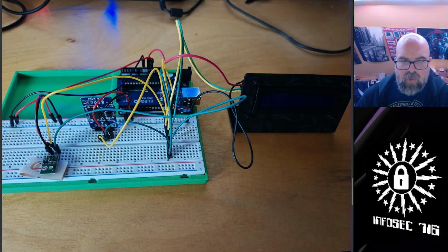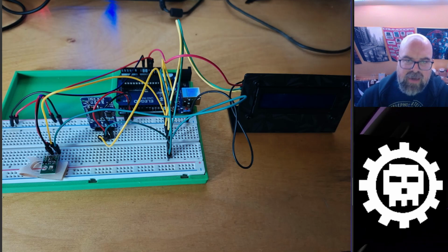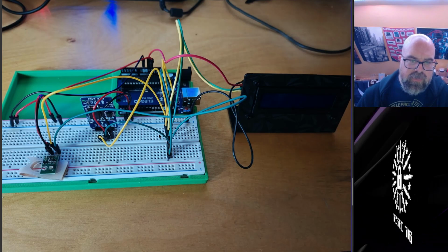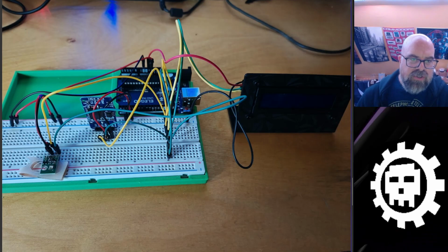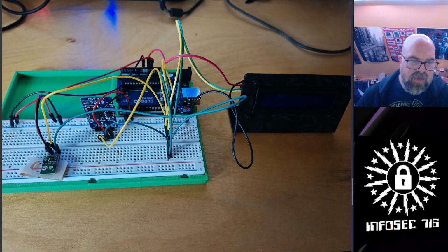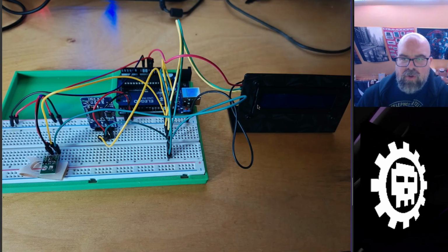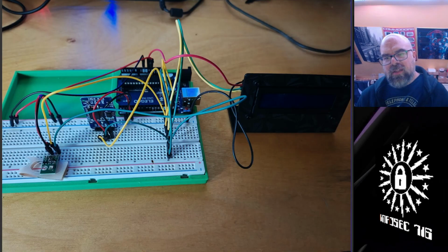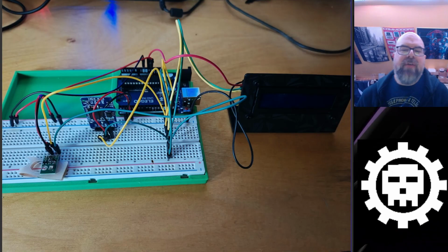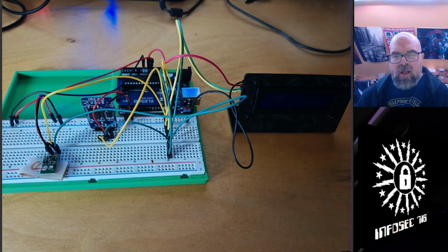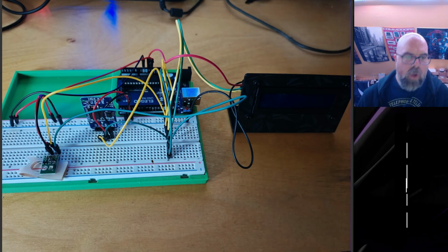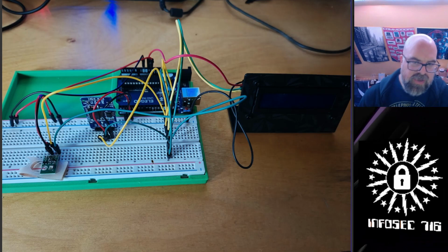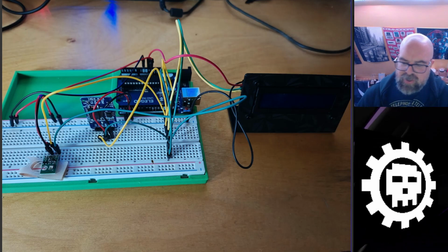Same thing with the green. The green wire from the serial data pin on the Arduino comes over to this row of tie points, and then you see we have 3 green wires, one going over here to SDA on the real-time clock, one going to SDA on the temperature sensor, and one going to SDA on the LCD backpack. So this is a good illustration of why it's nice to have I2C devices. They're all using the same protocols. They're all using the same wiring scheme. It makes it very simple and clear to hook up these sort of devices all to the same circuit.